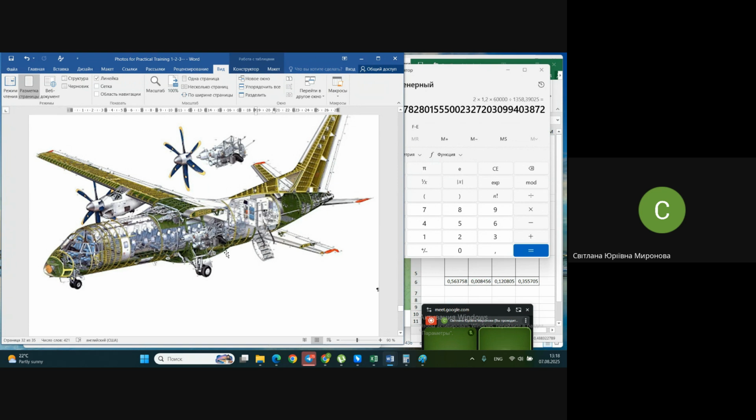If the skin is made of fabric or paper, in this case the spar works completely for 100% of the bending moment. And if we understand approximately that we follow the same inner structure and distribution of work between inner structure elements, we are going to follow this design, because other aircraft designers have already proven that it works.